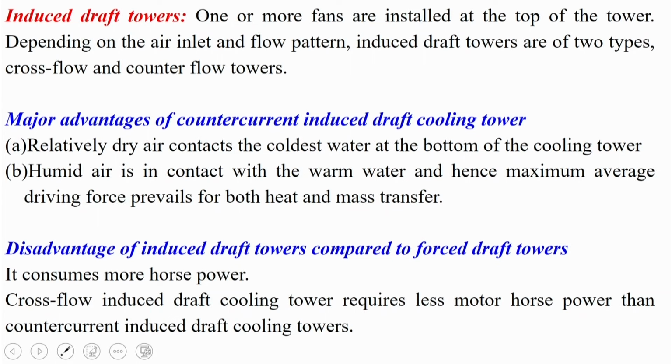The major advantages of the counter current induced draft cooling towers: there are two major advantages. One is that the relatively dry air contacts the coldest water at the bottom of the cooling tower, and another is that the humid air is in contact with the warm water, and hence the maximum average driving force prevails for both heat and mass transfer. So, these are the major advantages of the counter current induced draft cooling towers,